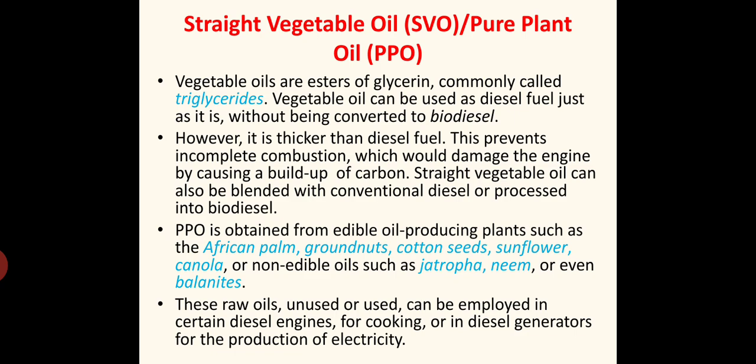Another difficulty is that on combustion it produces more carbon content than diesel and petrol. So of course the carbon deposit on the engine will be much higher, and also if the viscosity is high, atomization is very difficult. The fuel is actually atomized and injected into the engine. If the viscosity is more, it is very difficult to atomize, so the combustion process will be difficult.